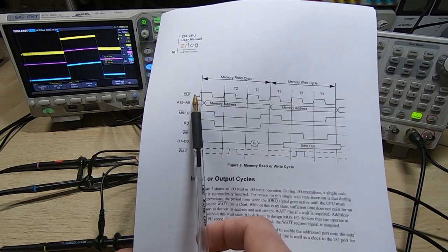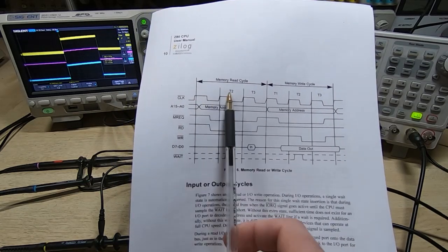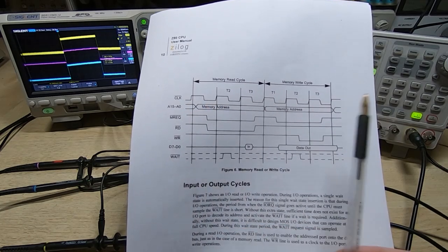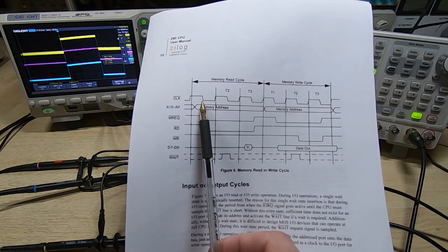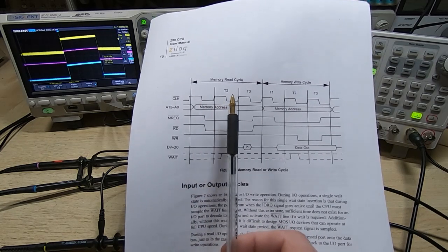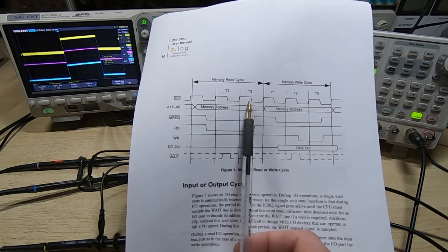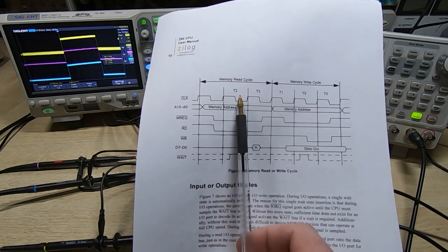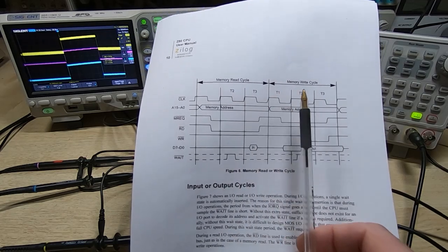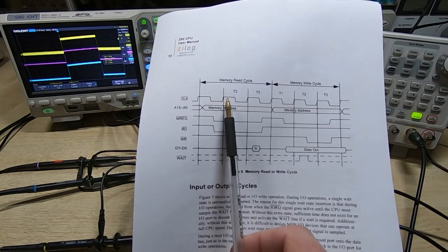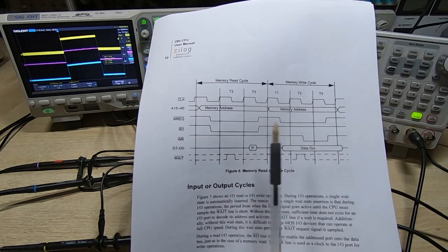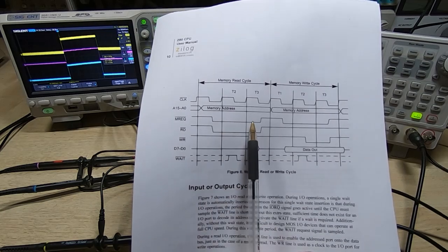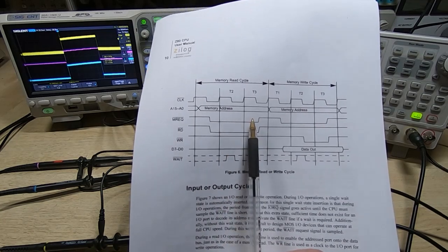And what we have, of course, is a clock that drives everything on the board. So almost every signal is derived from the master clock, and at some point that clock, usually divided down, goes into the processor itself. But the important thing here is that all the activities on the board are governed by these clock edges. So it might be a falling edge, it might be a rising edge, depends what you're driving, but from any given edge you will have a finite amount of time to perform an operation.